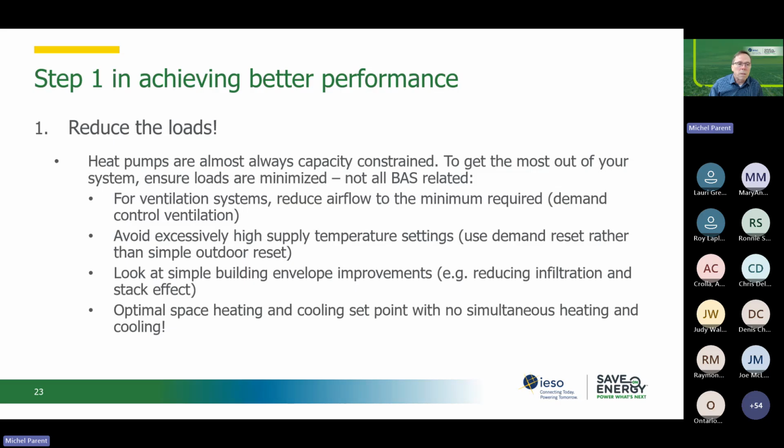That typically would be a mistake. It's trying to throw an efficient system, which is a heat pump, at a very inefficient operation. So you're trying to compensate waste by an efficient system. This is a recipe for poor economics for your heat pump system.